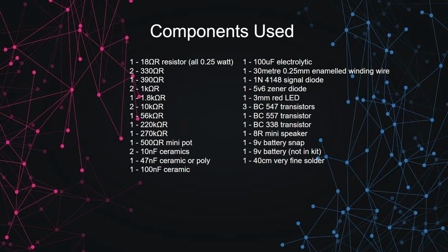Then coming on to the next capacitor, it's not ceramic but electrolytic, and that's of 100 microfarad. Then we have used 30 meters of winding wire of 0.25 mm diameter. Then we have used a 1N4148 signal diode, a 5.6 volt Zener diode, and a 3 mm red LED.